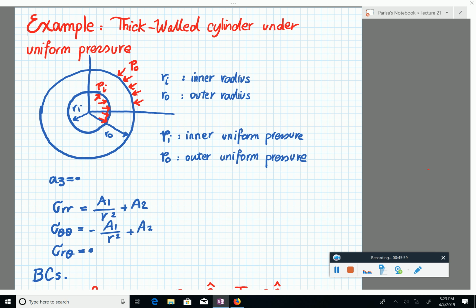To tell me, if I take R0 and I let it be very, very large. I'm sorry? That really scares me, because plane strain is not about geometry, is it? Somehow, you're right. But if everything is in a plane, right? Now I understand why you both said plane strain. So yeah, okay. It's something about geometry, but here that's not the kind of geometry. The geometry of plane strain is in the direction perpendicular to the wall. Right? So if this was an infinitely long pipe, then it was plane strain, no matter how large the R0 is.